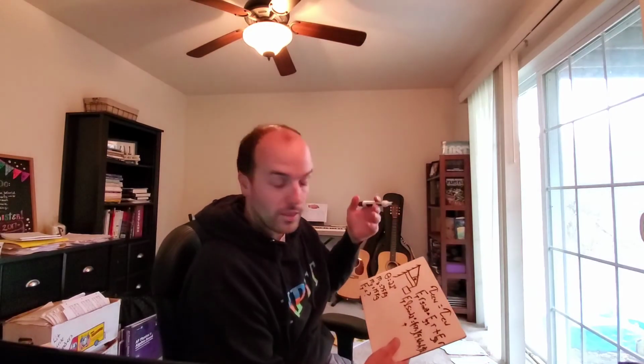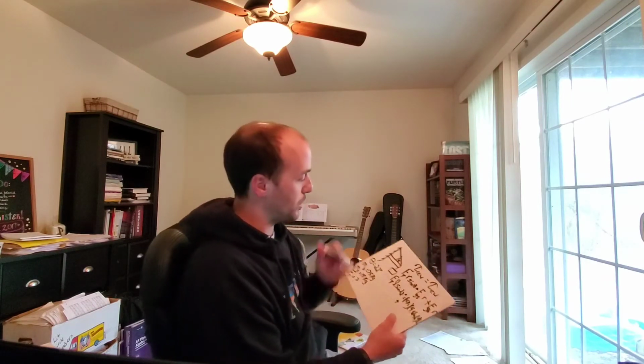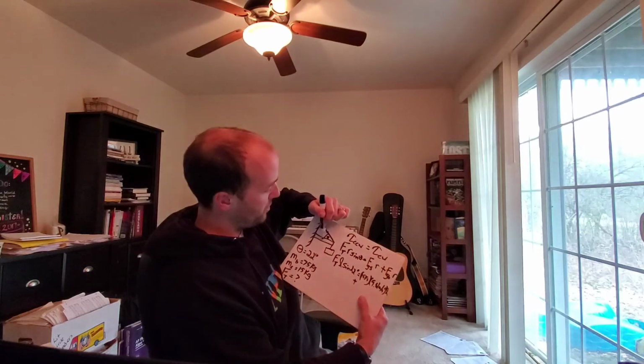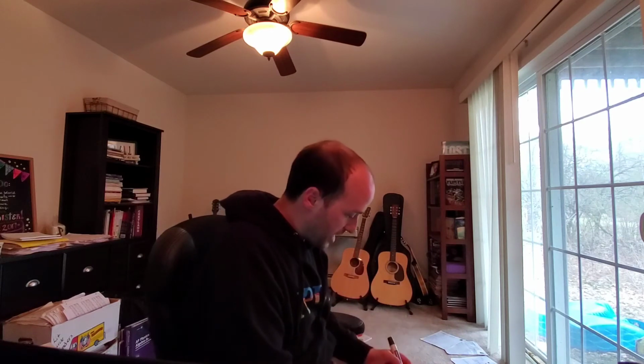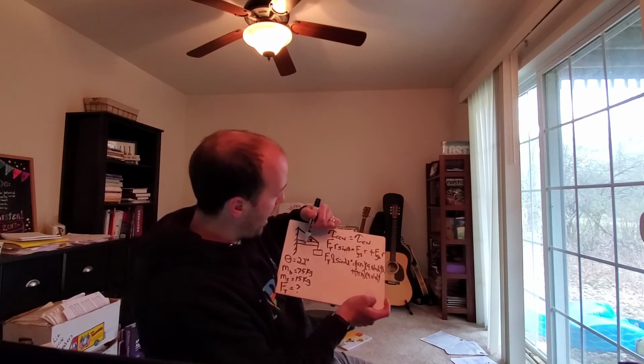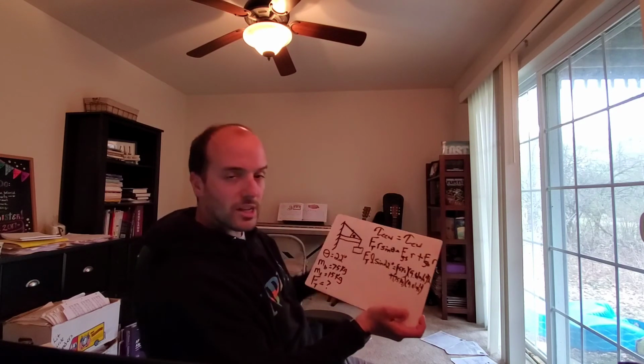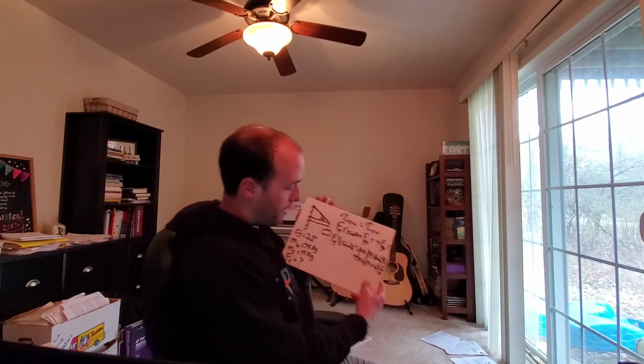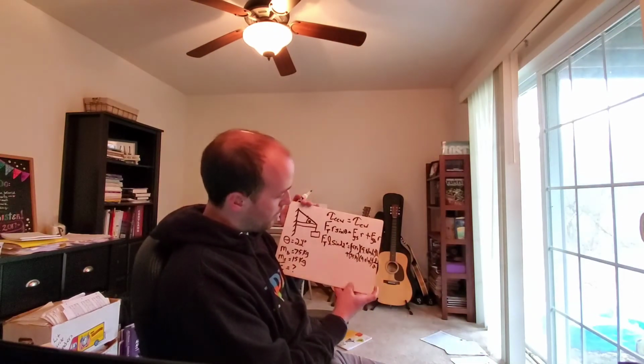Remember, the beam applies its force at the center of mass, so we measure from the pivot point to that center of mass. So we'll say that is our 75 kilograms times 9.81 meters per second squared. But our moment arm now is half of the length, so that's going to be L over 2.